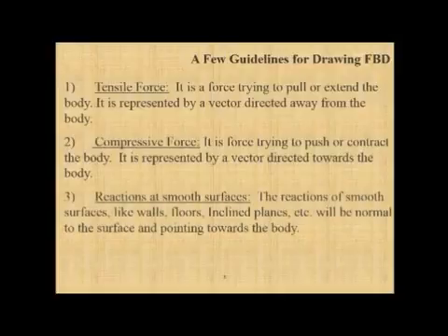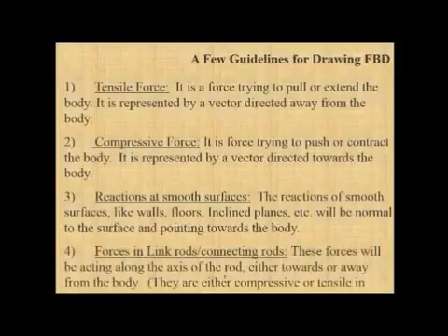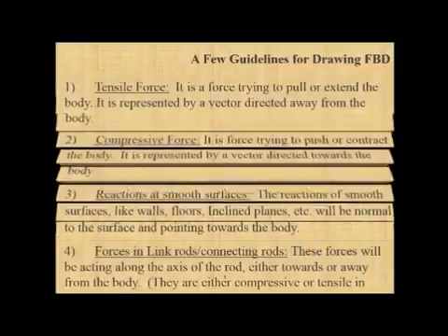The reaction at smooth surfaces, that is the reaction of smooth surfaces like walls, floors, inclined planes, etc., will be normal to the surface, pointing towards the body. Another is the force in link rods, that is connecting rods. These forces will be acting along the axis of the rod, towards or away from the body. They can be either compressive or tensile.